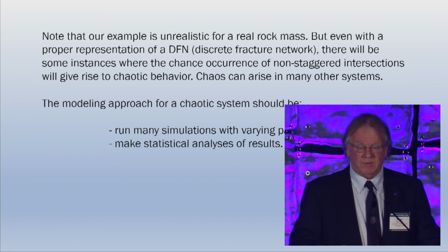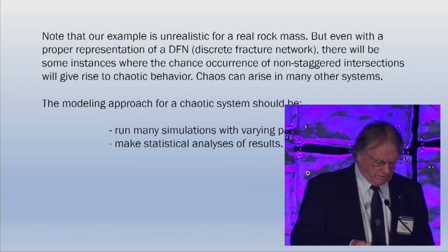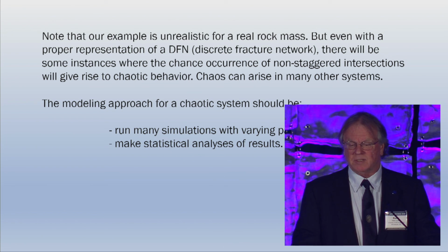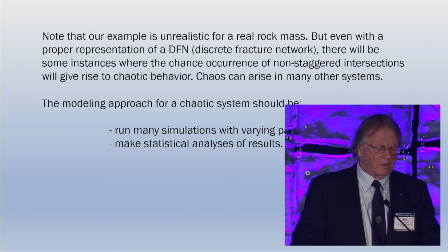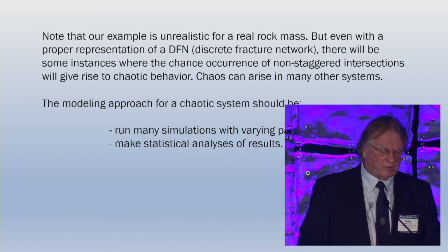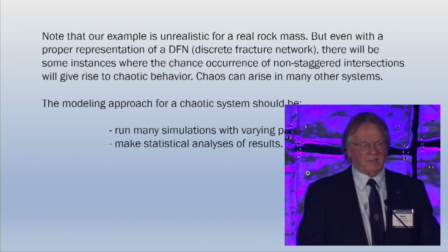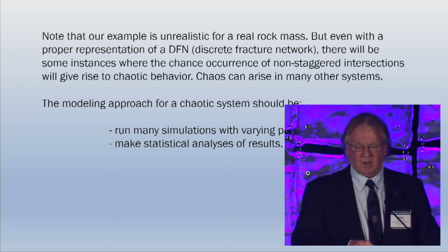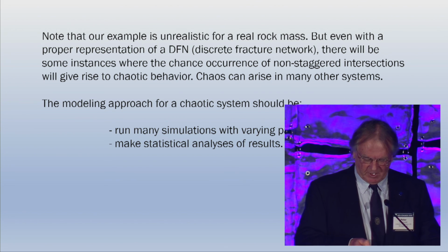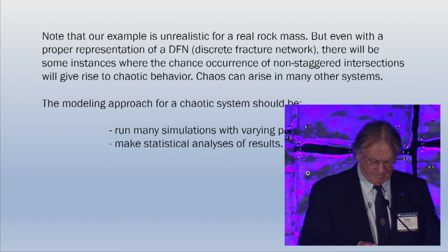This is the one I gave you an example for. So really, what you should do in this case is run many simulations with varying parameters and make a statistical analysis of those results. I'm always upset when I see people present just one simulation because it's so complicated they can't afford to do many more. But it's just pointless. You should do many simulations with parameter variations.